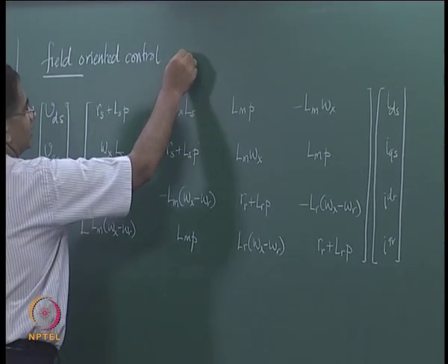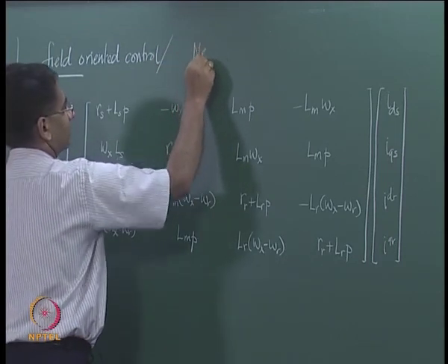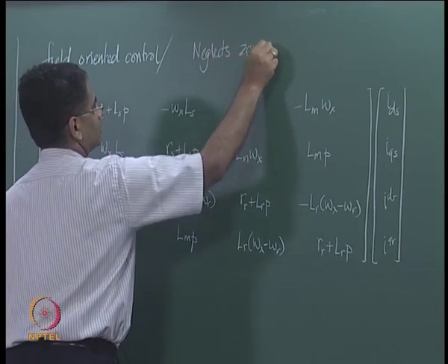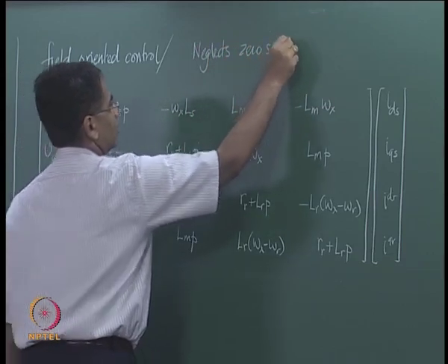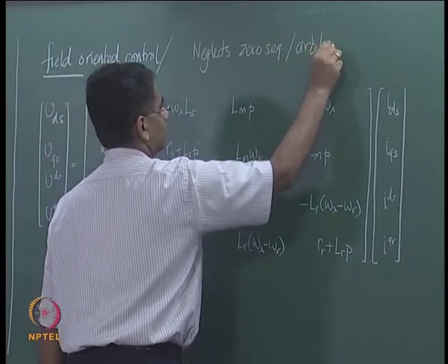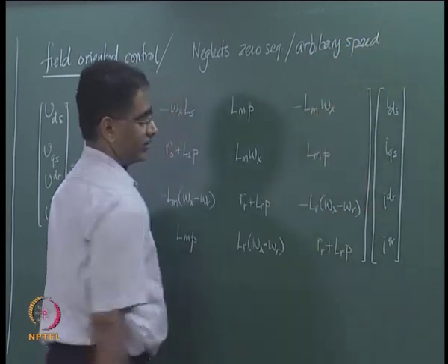So this set of equations neglects 0 sequence terms and is written for arbitrary speed of the reference frame.